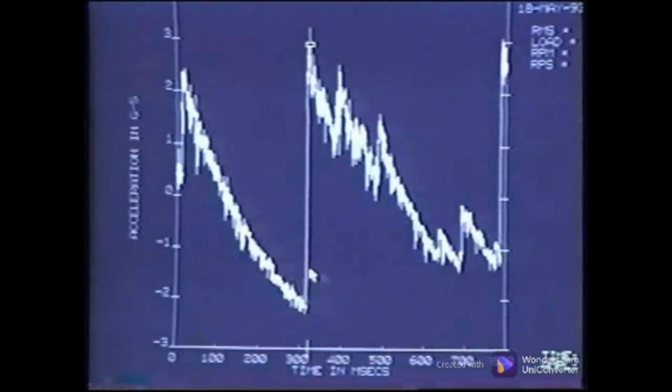This data was acquired during a routine monthly survey. If the program had been defined to keep only spectral data, this waveform, which provided the key to the diagnosis, would have been discarded. It is important to store the time waveforms during routine surveys.